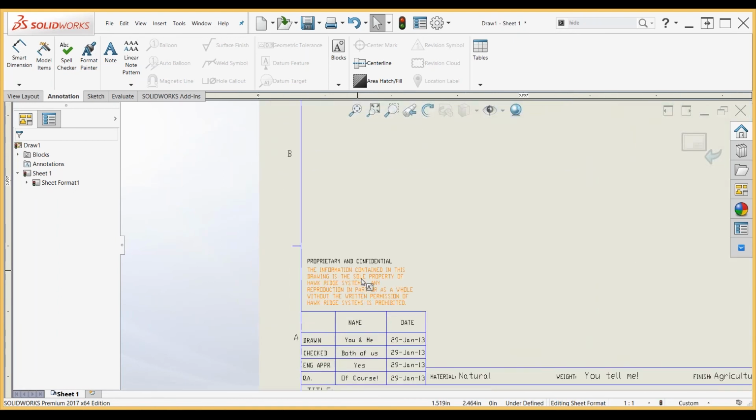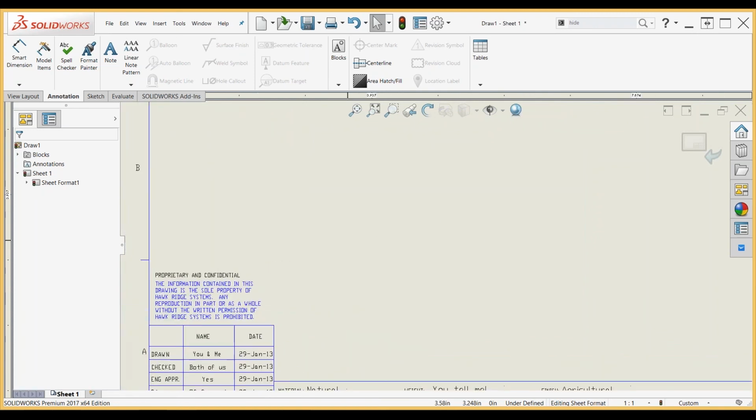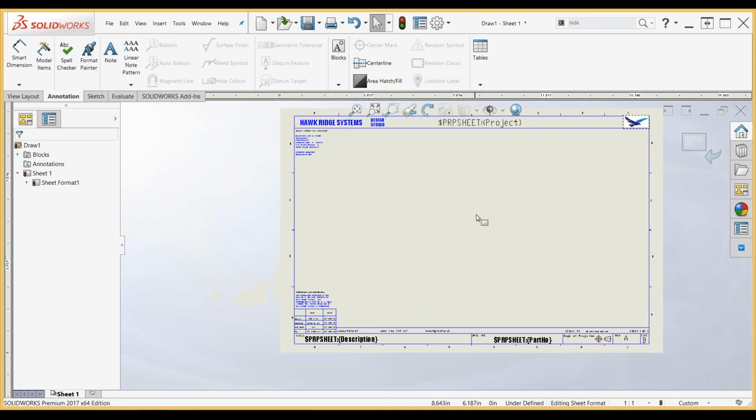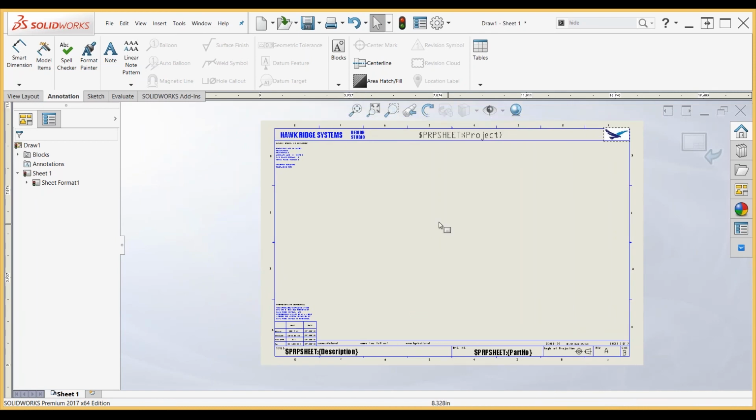Now if I'm using PDM or something, I can have my PDM workflows change the text or the value inside of this box. So by default it's going to be set for release, but maybe in my PDM workflow, once it gets pushed to the proper management, it'll automatically change that to ready for release, or just completely blank. So then nothing is coming across my screen. But this is hopefully going to make it impossible for anyone to accidentally make parts that aren't ready.